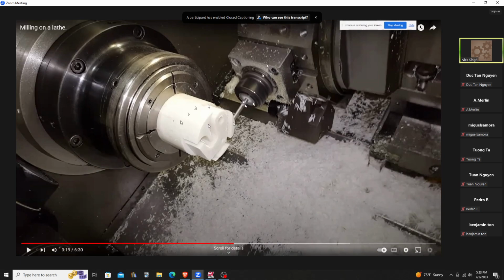And this is your collar, just like your milling machine. You have a collar, you can put any tool. You can put a center drill, you can put a tap, you can put an end mill. The other one, the one we used earlier, can work on the face and is called your axial, because axial is parallel to your Z-axis, and radial is parallel to your X-axis. So this is my radial live tooling right here.